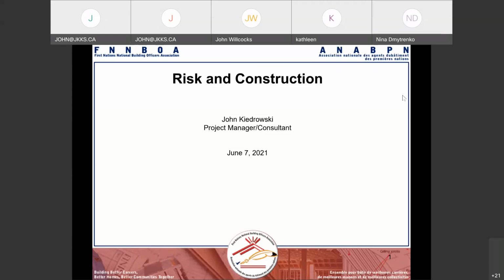In other words, don't pay too much in advance for the work that's done. You really need someone who has a good understanding of what percentage of work is complete and what percentage of money should be paid out to the builder, contractor or subcontractor. So just a few things to point out there. And generally, those payments should be based on code compliance inspections on a percentage.